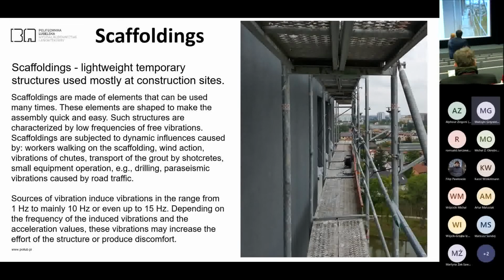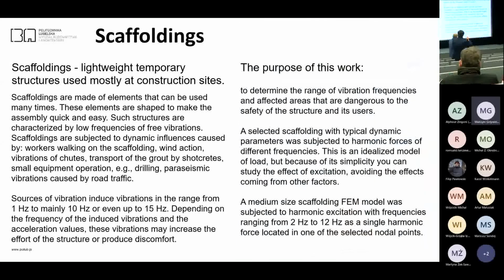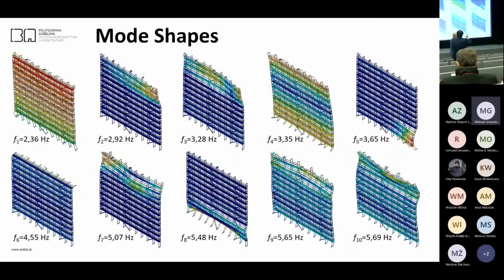And the second, as I understand from your drawings, the upper part of the structure was not connected to the facade, because normally it is a requirement that displacement in the direction counter to the facade is impossible, because on each level the scaffolding should be connected to the facade.